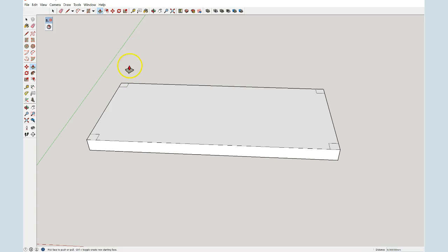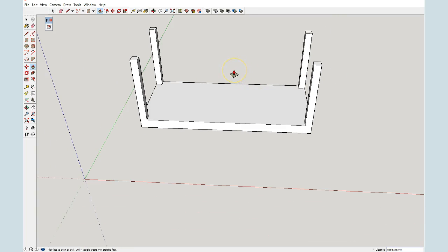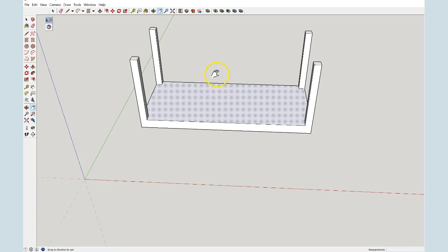So I'm going to use my pull tool again to select just the square, and then I'll pull it out 50 millimeters since I want my bridge to be 5 centimeters tall. So I'll type in 50 and do all 4 like such. There we go. And so that gives me my bridge. It looks like a table, but it will be my bridge.